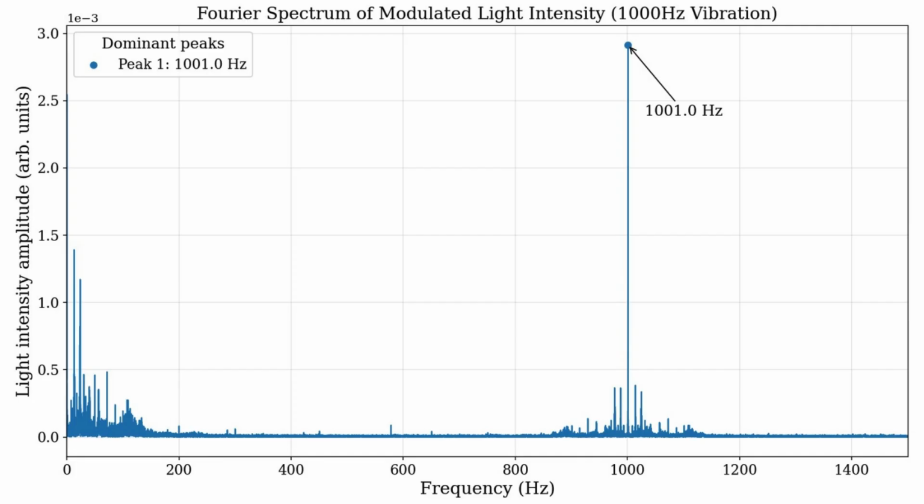And this is the plot of the FFT analysis of the data collected when a vibration of 1000 Hz is applied. As you can see, there is a distinct peak at 1001 Hz, which is sufficiently consistent with the introduced vibration of 1000 Hz. The interesting thing is that both 400 Hz and 1000 Hz measurements have an error of exactly 0.1%, which could also be a consequence of harmonic distortion or the spacing of the grid used in the FFT.